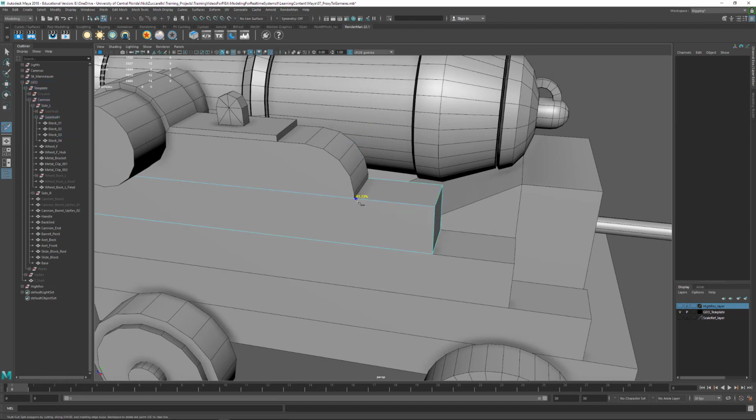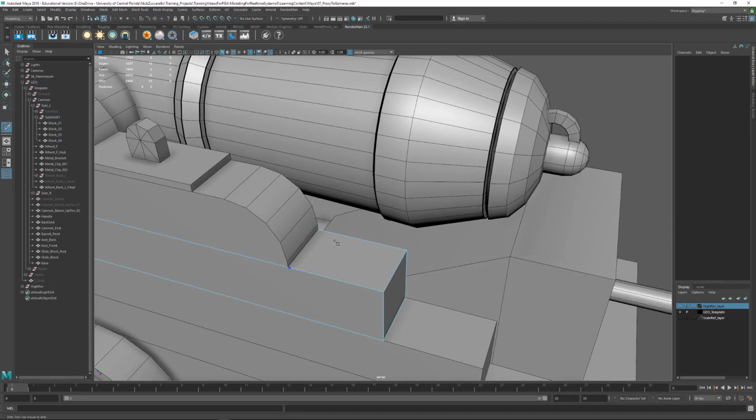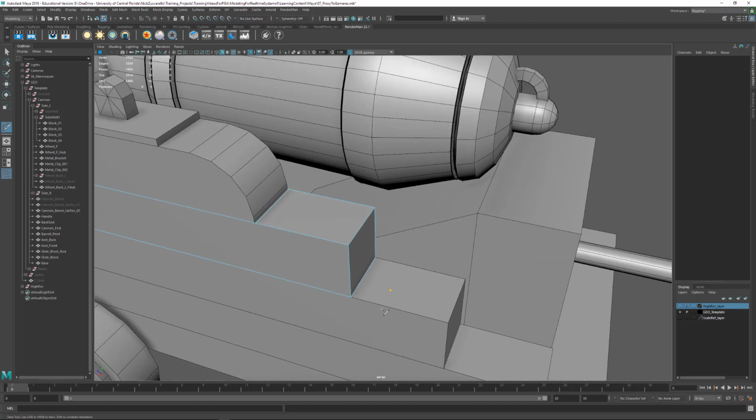And then we can drag from, let's just say from here, and I drag across, and if I hold down Shift and Control at the same time, it'll snap to a 90-degree increment for us for slicing across there. So I'll hit Q to go out of the tool, and then I could tap G for my last command. I'm just going to go right here, hold down Shift and Control, do that right there like that.